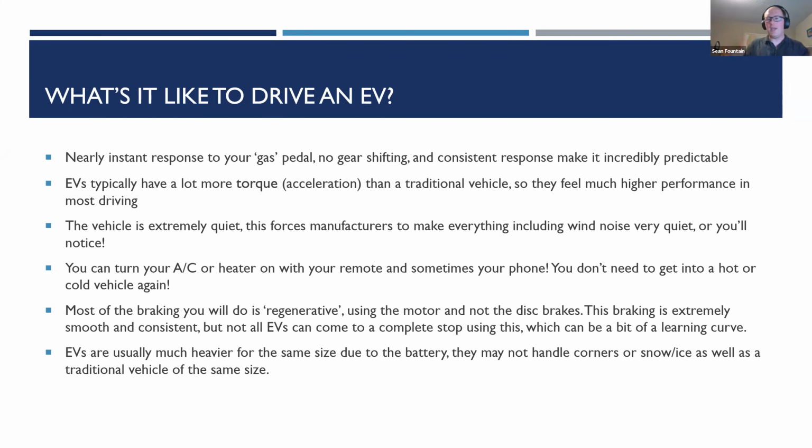So they do have a standard disc brake system. When you press the pedal down far enough, if they have that motor control on the brake pedal, or some vehicles don't have any motor control on the brake pedal, if they have that one pedal system, you press the brake pedal, it's pressing your regular old hydraulic disc brakes. And that's a quote unquote dumb system. It'll have ABS and stuff like that, which adds some intelligence to prevent sliding, but it will work even if the car is off. So that's an important safety requirement for all vehicles on the road. The hydraulic system works even if the car is off.